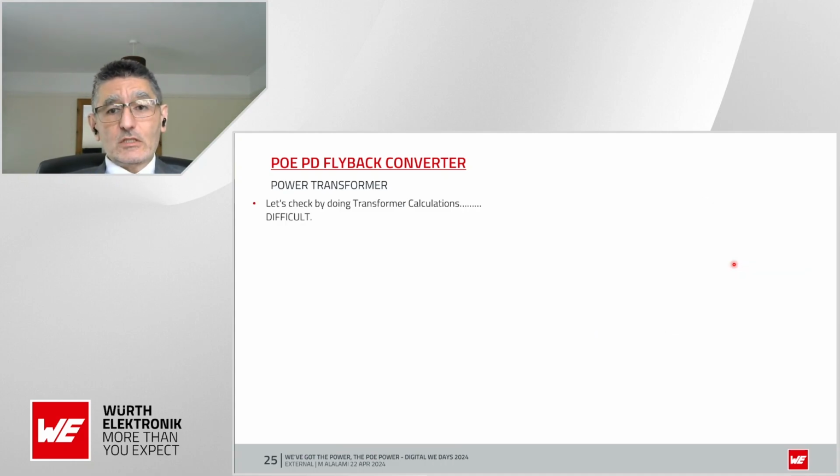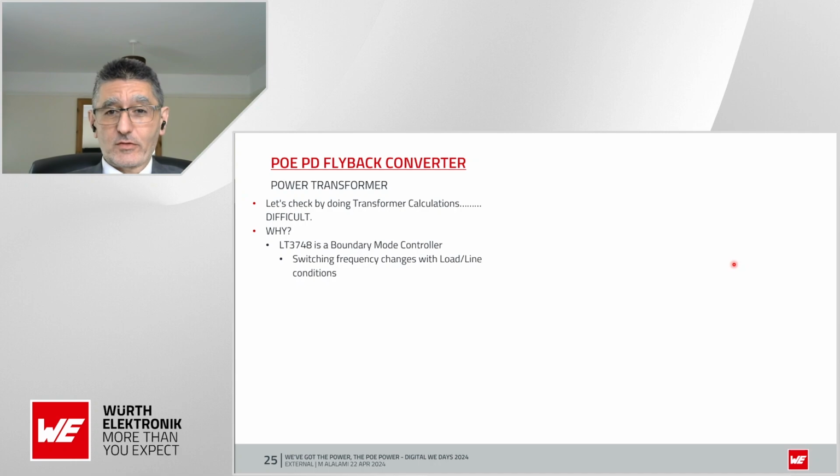Let's check though. Let's do this by calculation. Let's calculate if the transformer is going to be okay or not. This is difficult. Why is this difficult? Because the LT3748 chipset that we are using is a boundary-mode controller. In other words, the switching frequency changes based on load and line conditions. So that's making things more complicated.